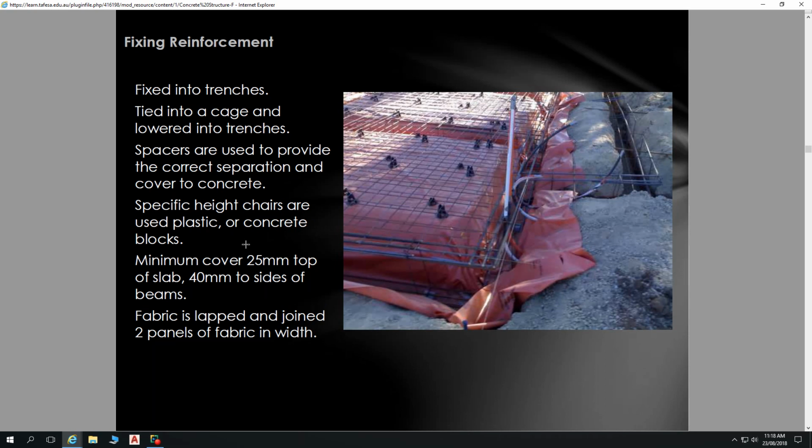So we make sure our bars sit at the top and at the bottom of the beams. With corner details and whatever, you do have various different considerations. Wherever you've got re-entrant corners, you've got two levers that can work against each other or in concert with each other to crack a corner. And sometimes you have extra bars placed diagonally in those sections.